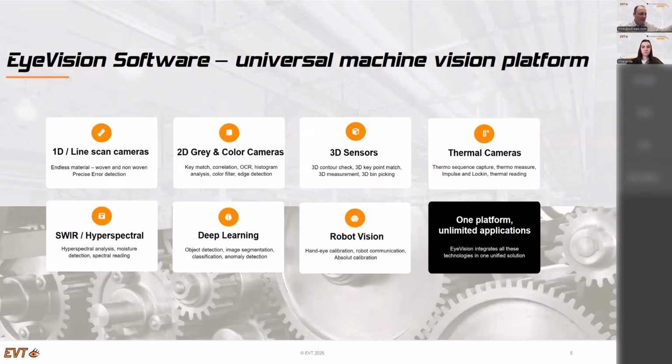They buy a high-resolution camera with 12 megapixel, and buy of course the cheaper lens for 5 megapixel, because 5-megapixel lenses are cheaper. And finally, they wonder why their measurement resolution is in the range of the 5 megapixel and not of the 12-megapixel camera, simply because of the lens. So the lens is an important part of the machine vision application, as important as the camera.